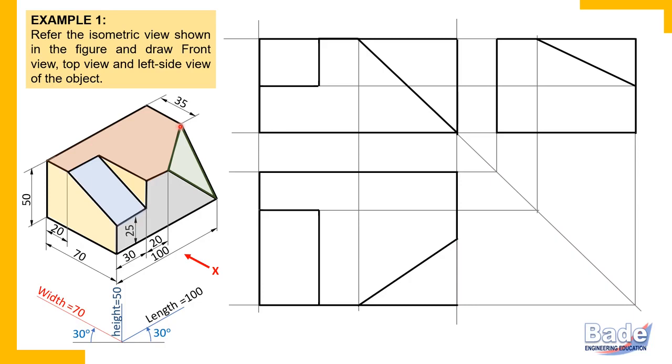Where is that back side? Here. Not extreme back. So from back, parallel to width, 35. So this is first of all back side. And from the back side, parallel to width, 35. So you measure 35 millimeters here. But try to understand, this edge is already there in the top view, because this edge is the edge of this principal surface.